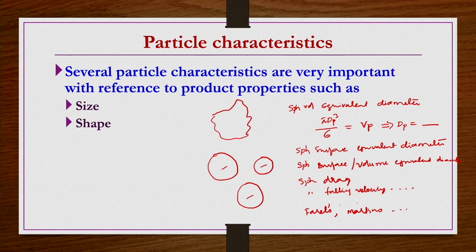However, this can be answered by the experience of the process engineer involved in the process, or it can be based on the application. Let us say you have cyclone separators, then the sphere Stokes equivalent diameter would be sufficiently reliable. If you have irregular particles, like flow through packed beds etc., then the sphere surface to volume ratio equivalent diameter would be more reliable.